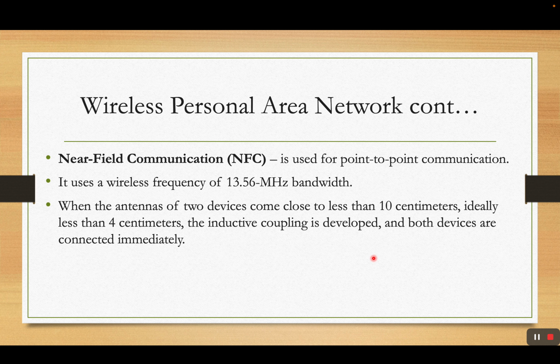Now, the final thing here is near field communication, NFC, used for point-to-point communication like Apple Pay. It uses a wireless frequency of 13.56 megahertz. When the antennas of two devices come closer than 10 centimeters, ideally less than 4 centimeters, inductive coupling is developed and both devices are connected immediately.